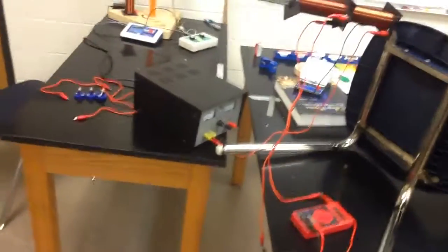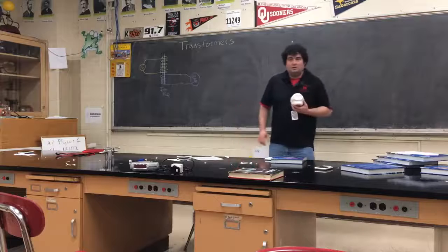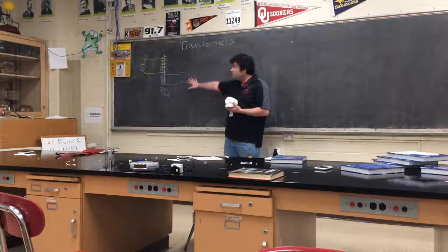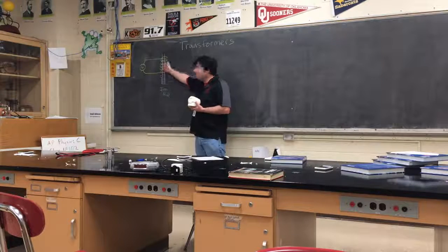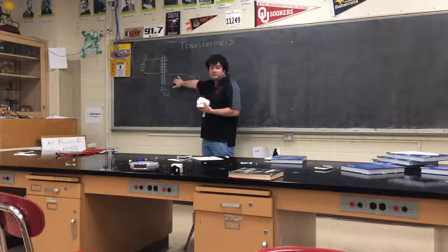In order to continuously make electricity in this coil, we have to be continuously changing the magnetic field inside it, which means we need to be continually changing the current in this coil. That's why alternating current is required. So there's other better designs for a transformer than this that capture more of the magnetic flux coming out of the input, which we call the primary, and direct it into the output, which we call the secondary. But we can use this model for now.